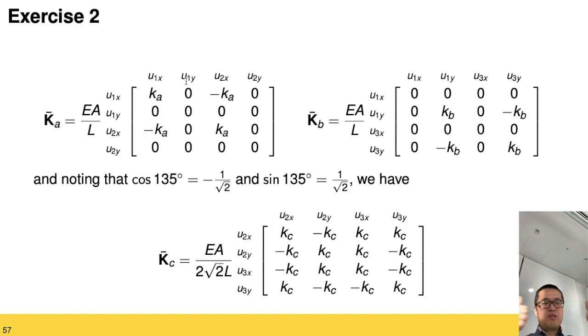There's nothing in the y direction because the bar is going horizontally, so that gives you 0. Similarly, U2x is the value of the spring constant in the diagonal bit. Because you have the coupling between U1x and U2x, which is only moving horizontally, that gives you minus Ka in the off-diagonal matrix elements. And everything else is pretty much 0.